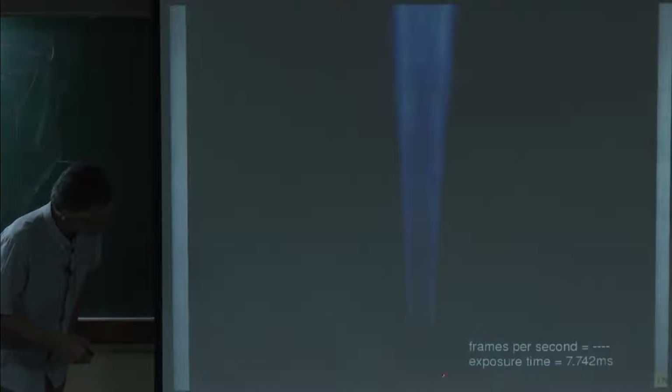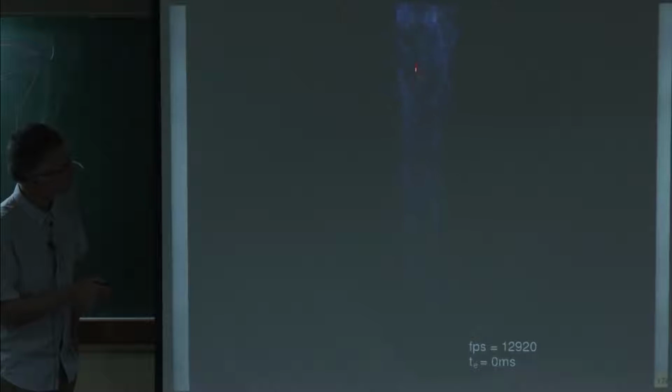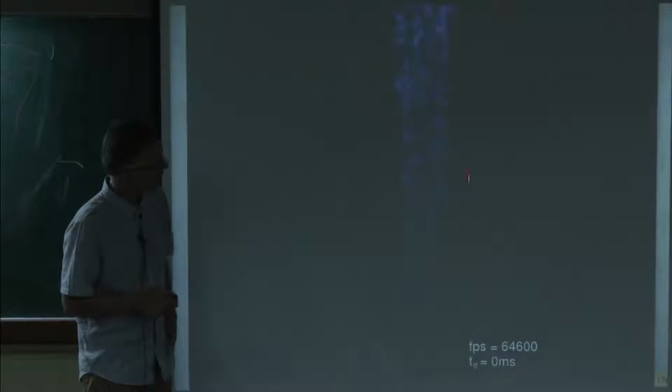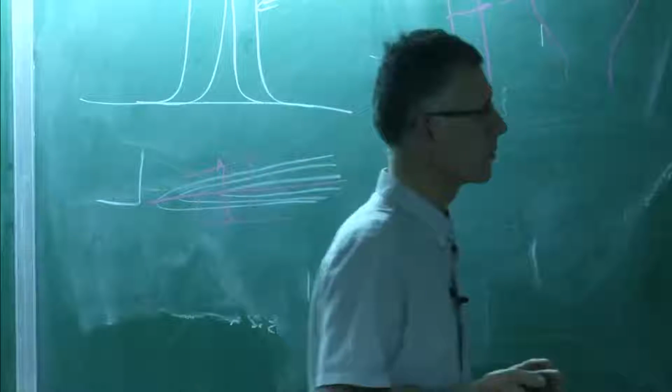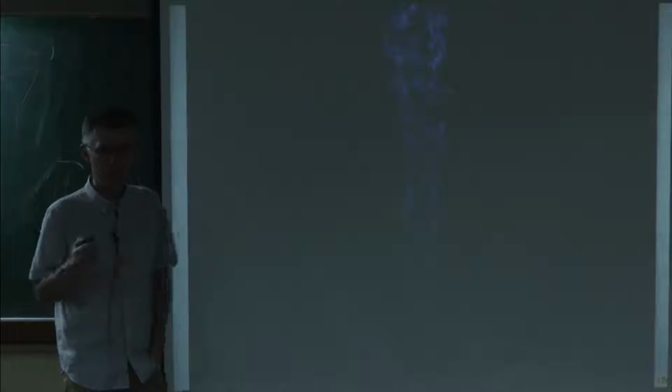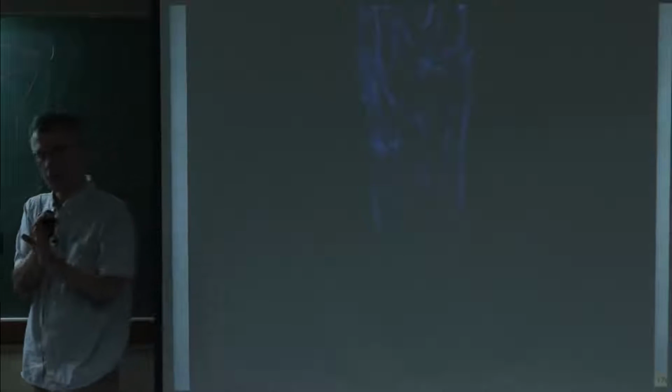So this is a jet here of fuel, and there is quiescent air, and this is LES, and you see the structures here on this flow. It's an LES, and you see how long those flames are, and you see how lazy they are too, and now it's slowed down, and you can see these structures here. And we believe that many of these structures actually are iso Z surfaces where we are at the stoichiometric value. So this is where combustion takes place. You remember what was said yesterday, that these zones can be split in two, a lean zone here, a rich zone inside, and in the middle, the flame. Okay, that's where the flame is sitting.